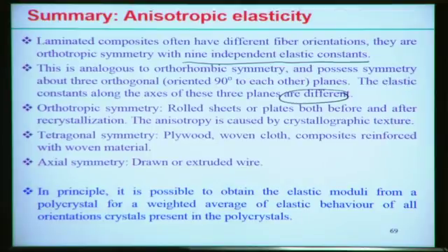But orthotropic symmetry we generally understand, or we observe, in rolled sheets or plates before and after the recrystallization. The anisotropy is caused by the specific crystallographic structure in this specific rolling process. So we can consider this anisotropy as the orthotropic symmetric behavior in this case.